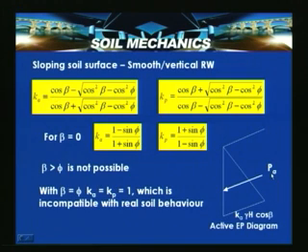So by substituting in sigma a is equal to Ka gamma z cos beta, at z is equal to h, we will get the earth pressure ordinate parallel to the slope surface of the fill, that is Ka gamma h cos beta. The resultant thrust is determined by Pa, which is indicated here.